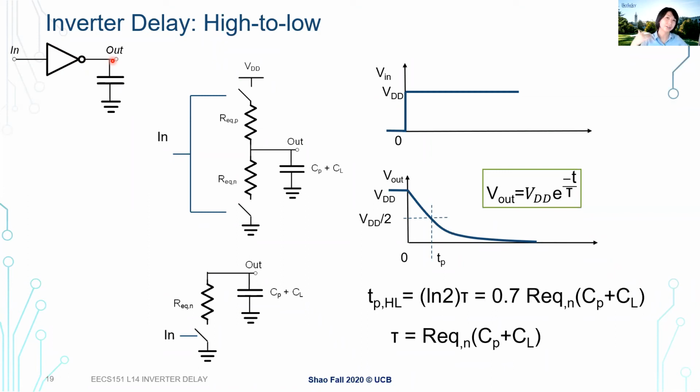We talked about how we can abstract our transistors as a switch with a resistor, right? So once we start talking about delay, instead of looking at this abstract gate, we decompose it and use our switch model to represent both our PMOS transistor and NMOS transistor. An inverter is basically a PMOS and an NMOS. The NMOS does the pull down part, the PMOS does the pull up part, and the same input is applied to the gate to either turn the switch on or off. So here is our switch model for our inverters.